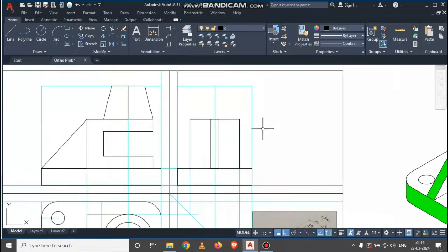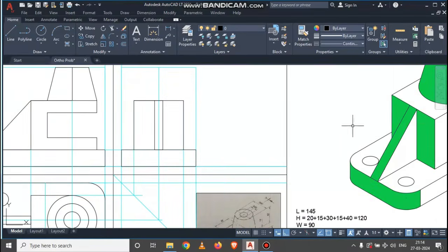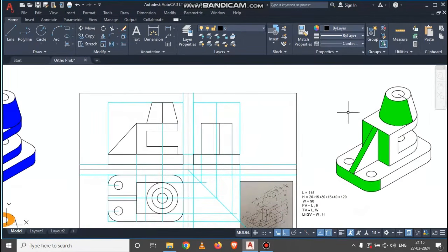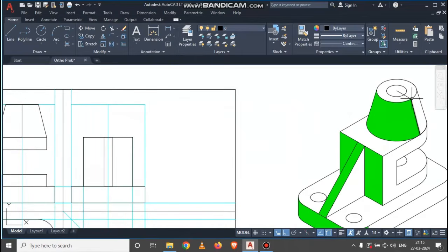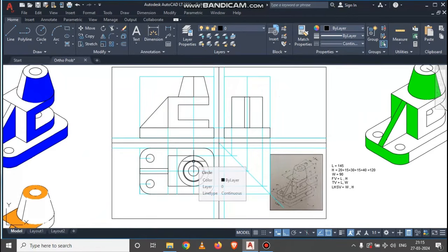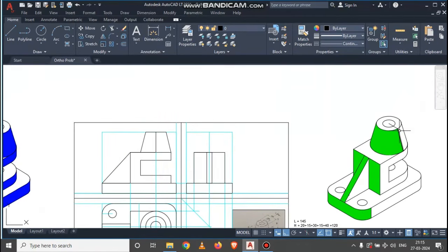Now you can imagine we are done with these rectangles on either side. Now to have the representation for this conical surface that will be visible while looking from the left hand side view, we just need to understand these extreme two points. We need to transfer them in a vertical upward direction, so that we can connect this base corner point in an inclined manner to this top circle corner point, and that we are getting from the top view. So this middle circle will represent this upper circle.